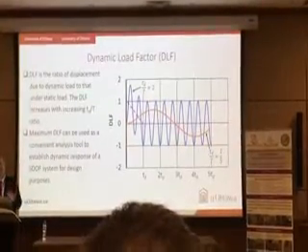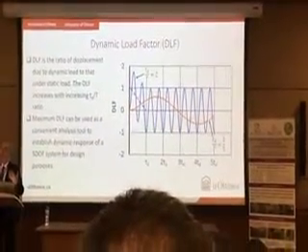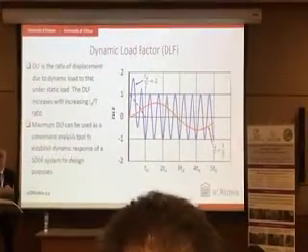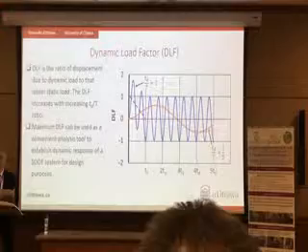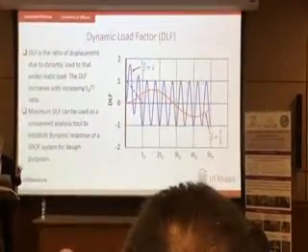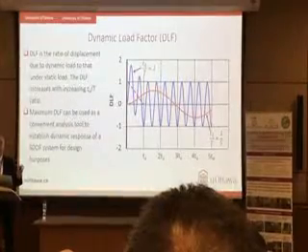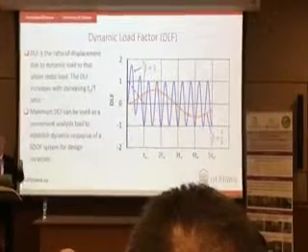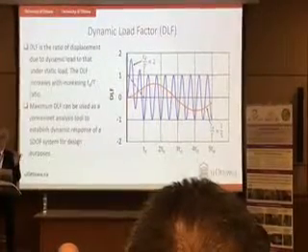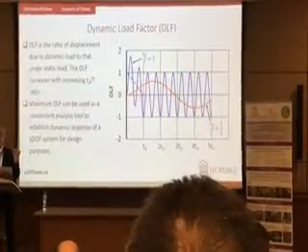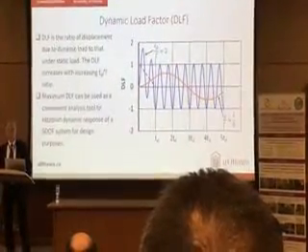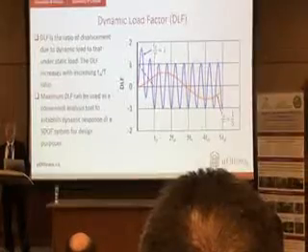Okay? Now dynamic response divided by static displacement, or dynamic displacement divided by static displacement, is referred to as dynamic load factor. And dynamic load factor is one factor that is very convenient. All I have to do is know dynamic load factor. I can then do static analysis multiplied by dynamic load factor, get displacement under dynamic conditions. So it's a convenient design tool, especially if I plot maximum dynamic load factor.